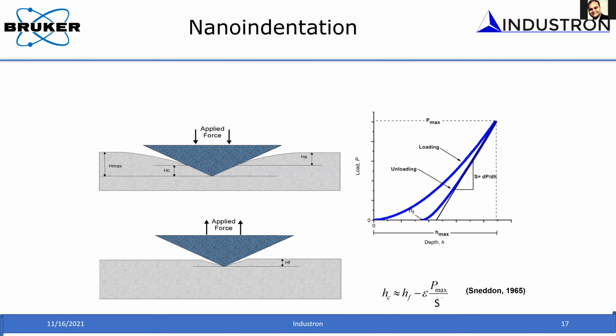So the geometry around that indenter reflects the state of the material, whether it has high defect density or not. For example, if you take a copper sample, and the copper is well annealed so that it has very low dislocation density, if you do an indent experiment on that, what you will see is a sinking phenomenon. For example, the indent has kind of sinking.